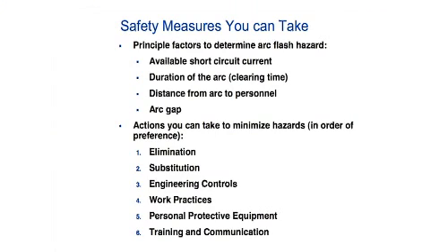Okay, safety measures that I perceive that all customers should be taking. All right, we need to understand all of these. These are the 1584 calculations. One of the key elements in here is the clearing time of the breaker itself. Because as I go forward, you'll see very quickly that the lowest amount of time will end up with the lowest amount of arcing energy. And that's critical to reducing the PPE requirement.